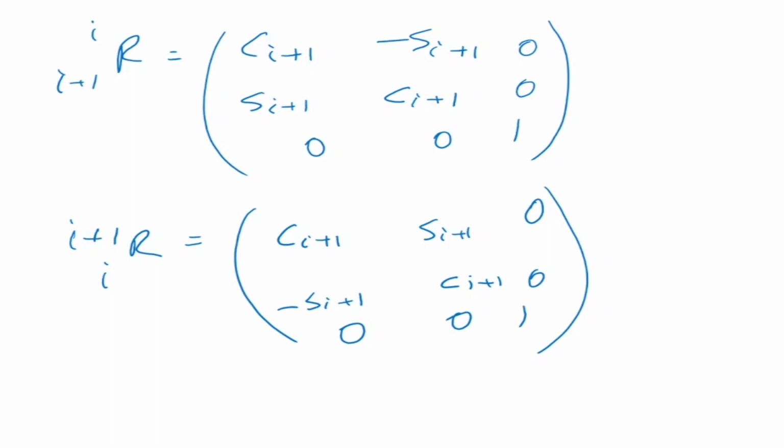The base frame is not moving. Hence, we are giving angular velocity and acceleration to be 0. In a moving system, for example a space robot, the base frame can also have a velocity, but in our case we are saying it is equal to 0. How is gravity being included? Gravity is being included by saying that there is acceleration due to gravity in the y direction.